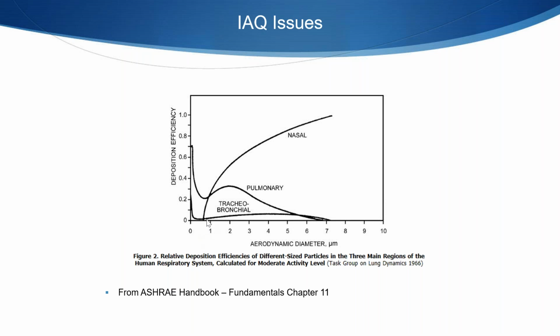So really anywhere along that aerodynamic diameter, there is a tendency for our respiratory system to take these particles in. And why that's important to me is because there's a lot of discussion about different technologies, and some of those technologies focus on making particle sizes larger, or that these large particle sizes that did get through our filtration system may not be as harmful because they'll drop faster. Well, that can be true, but they're still active for a period of time. So that's still an active viral particle or bacterial particle that's floating around in the space that your respiratory system is receptive to at these various sizes.